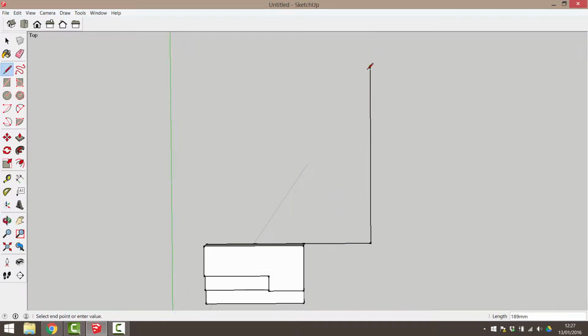Now I want to drag in the direction of the red axis. To constrain my drawing only to the red axis, I can click on the right arrow key on my keyboard. This constrains my drawing to only the red axis. I'm going to type in 12,000 and press enter. A way to remember this: right, red, meaning right arrow, red axis.